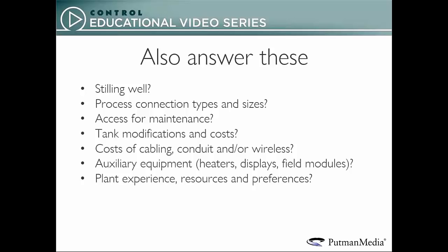There are other ways to measure level, such as weighing the vessel and its contents with load cells. In most applications, any one of several different level technologies could be made to meet the requirements. Often the deciding factor is the life cycle cost, which includes the costs of installation, maintenance, and calibration. Understanding all of the installation considerations at the start will keep a project from exceeding budget and help minimize headaches.